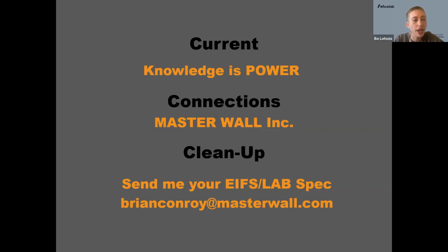But I see Charles Shaw had asked about pros and cons of each, and it looks like somebody answered: EPS is lower cost, greater availability, and easier to install with EIFS. XPS has a higher R value per inch and greater compressive strength. So I think that is a good thing for everyone to note.